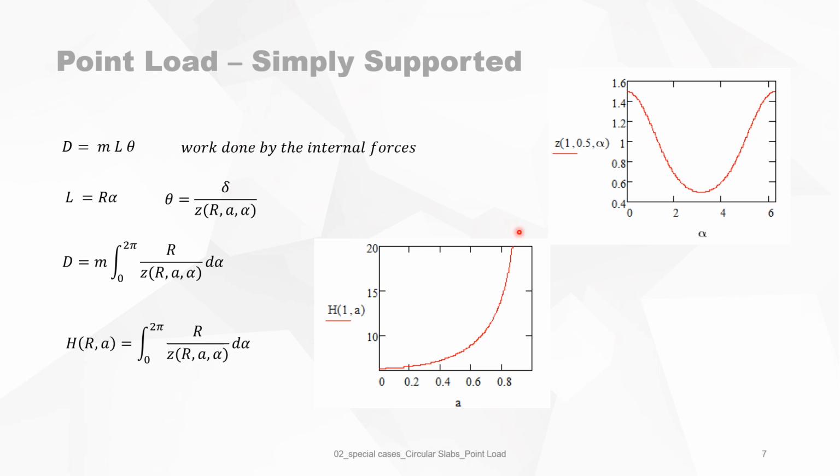Just when the point load is very close to the slab edge, the forces will go directly to the edge, or the yield lines will be different. Also, the angles of rotation will be too big to apply all those systems. So that's why we stay away from the edge, because those results are not very accurate.